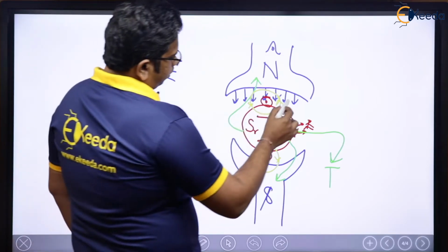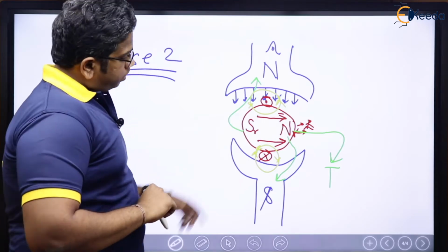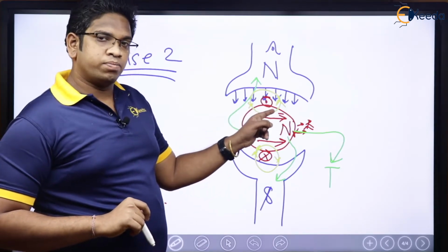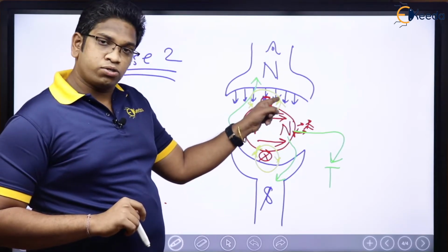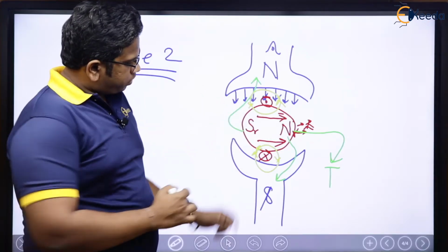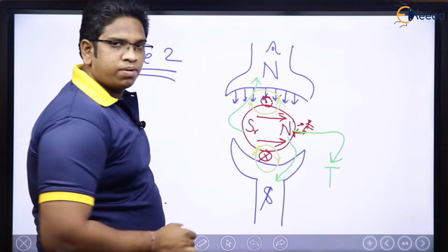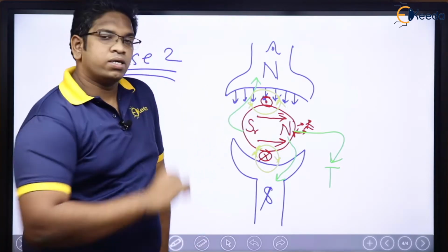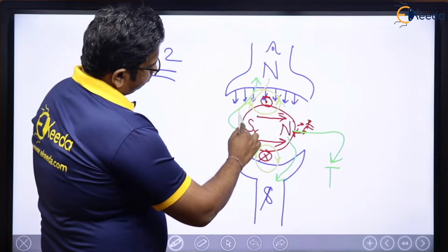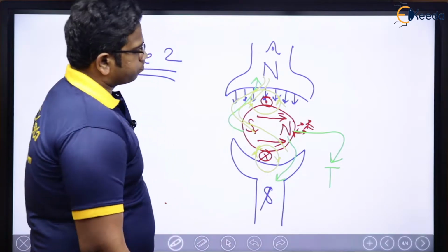Now see here. Here if you see in this particular area, what is happening? This rotor flux and the stator flux are opposing each other, which means flux here has to be approximately 0. If you see here, what is happening? Rotor flux is in this direction, stator flux is also in the same direction, which means flux is going to be aiding there, which means this flux has to come like this, right? This flux has to come like this.